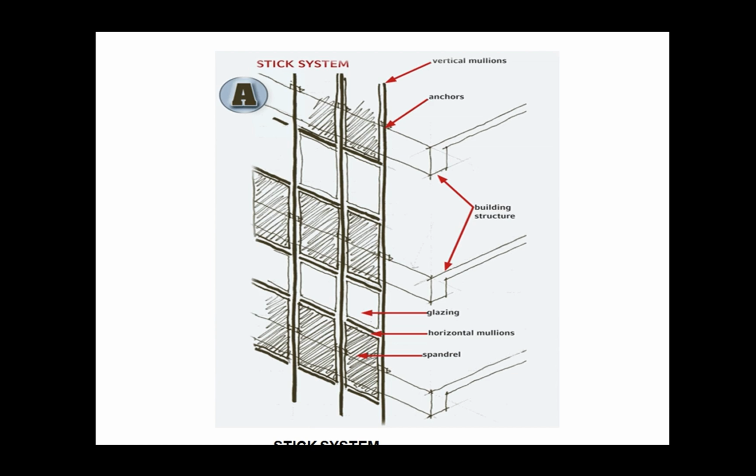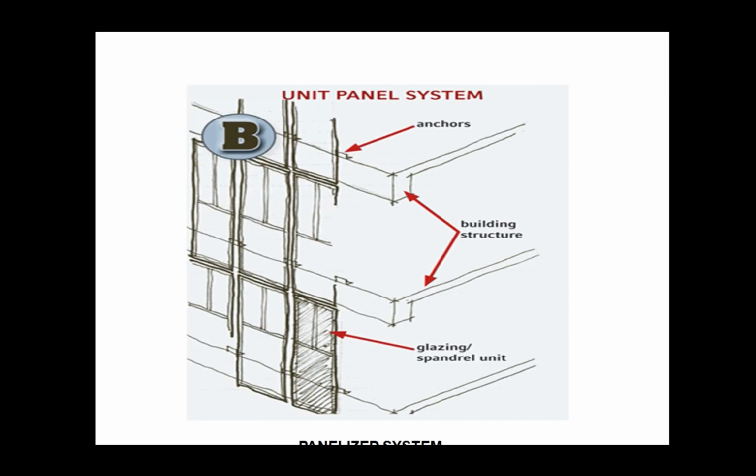Moving your way over, sliding it down, and then capping it with the top mullion. Using that top mullion, the other side of it is the base for the next layer of glass. Sliding it between two verticals and then putting another horizontal. And what you see there is the hopping between the vision panel and the non-vision panel going on up.